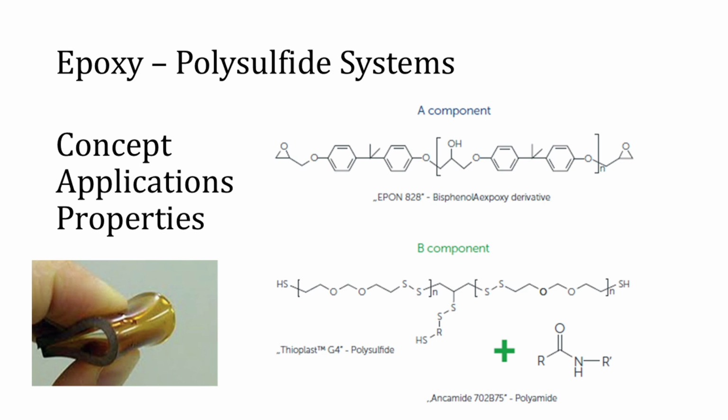on adjacent surfaces. When designed properly, polysulfide epoxy blends exhibit a range of enhanced properties. They offer improved adhesion to challenging substrates such as aluminum, rusty or oily steel, and even wet concretes. These blends demonstrate enhanced durability, particularly in humid or corrosive environments, along with better chemical resistance against fuel and oil. They also provide improved impact resistance and maintain flexibility down to approximately -30 degrees Celsius depending on the epoxy resin used. In terms of specific uses,